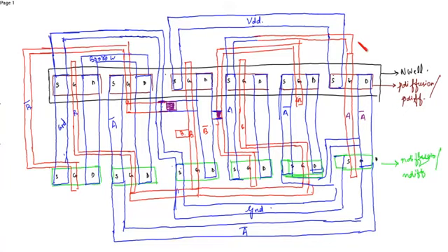Okay. And you have to place a poly contact here. Okay. Now this is connected. Next you have to connect the output. Output is obtained from the drain.